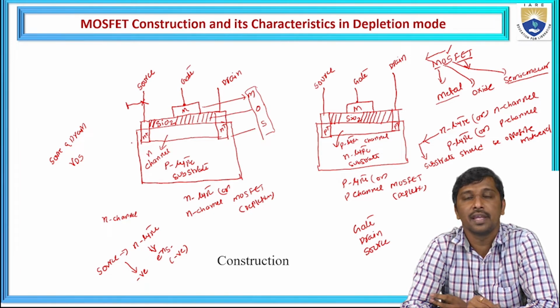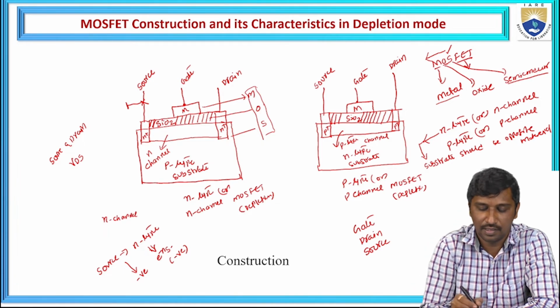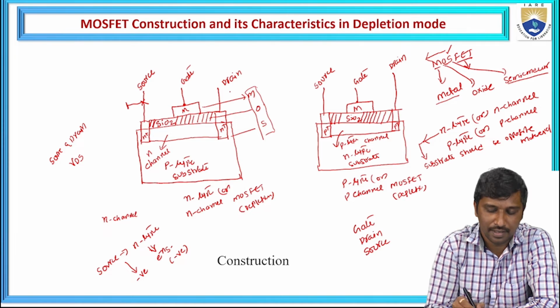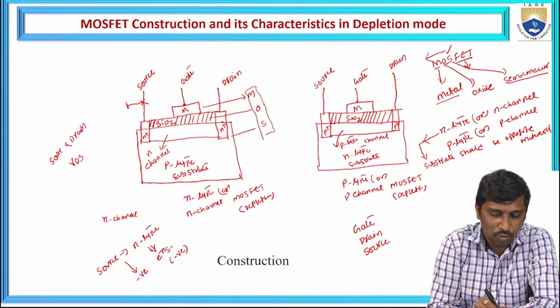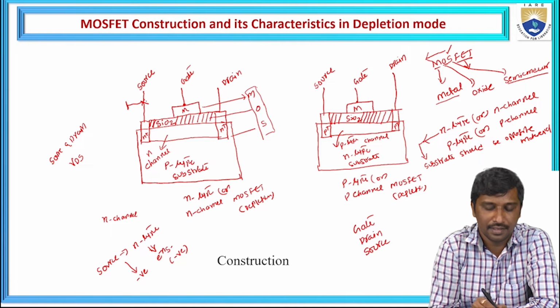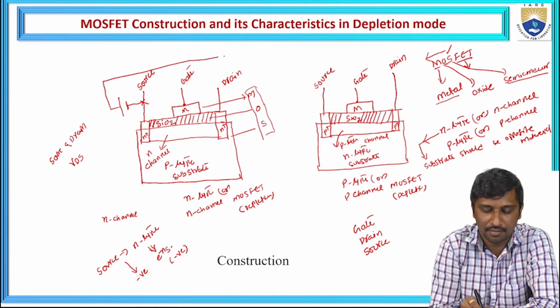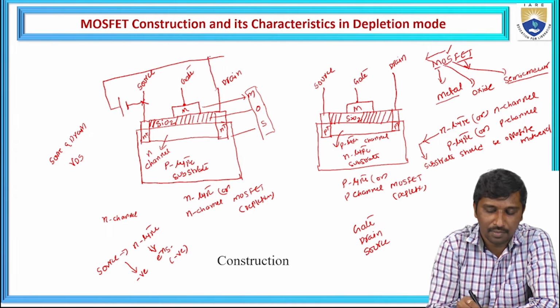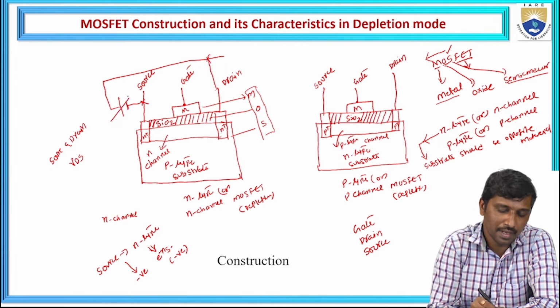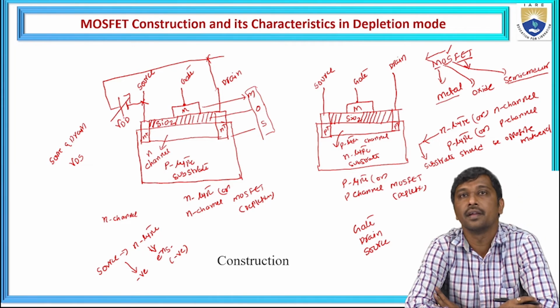So we need the charge carriers repelled from the source to all reach the drain, which means the drain is biased with the positive pole of the battery. So the negative pole of the battery is connected to the source, and the positive pole is connected to the drain terminal. This biasing voltage is represented as V.